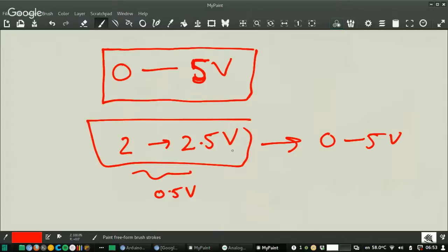No, I wasn't saying this. I have read in the datasheet or somewhere that the ADC is very sensitive to voltage. The measuring range is -1 volt to VCC plus 0.5 volts, that is 5 volts plus 0.5 volts. If you give a voltage greater than this, it might damage the ADC, so whatever sensor reading you get, you have to keep it in the range of -1 volt to VCC plus 0.5 volts.